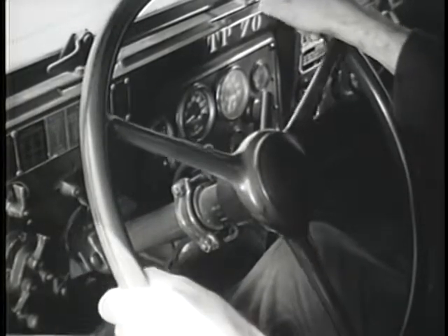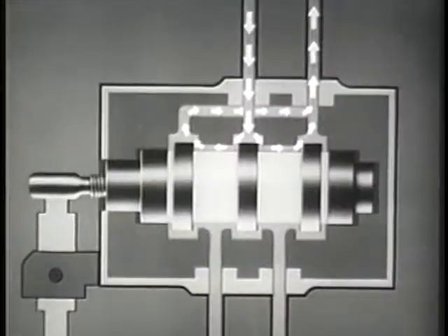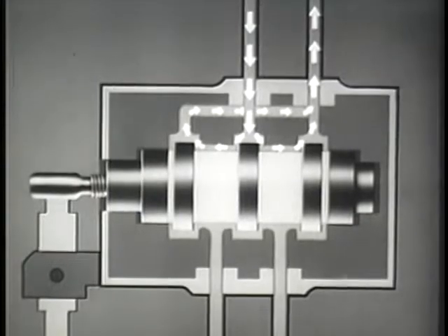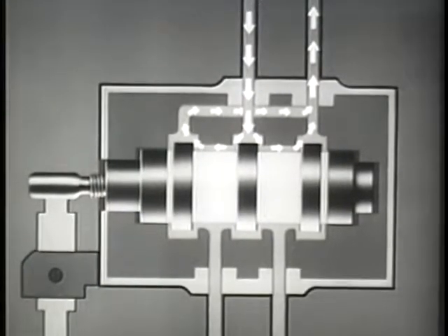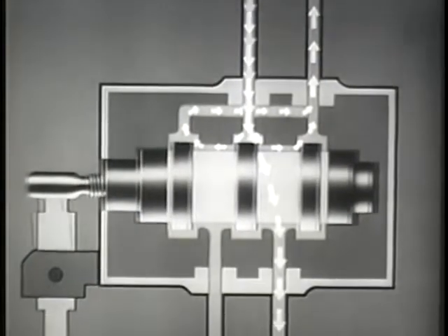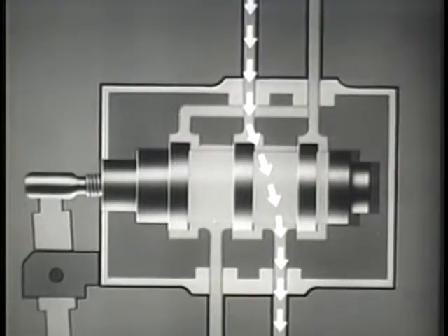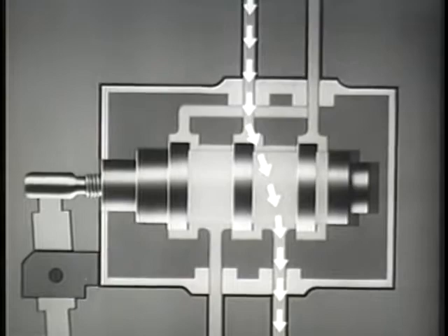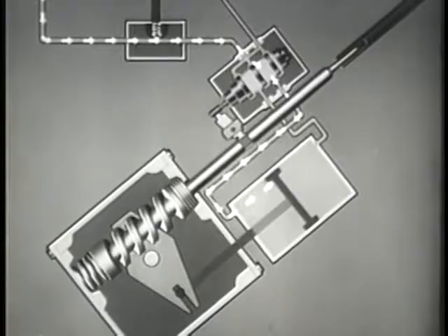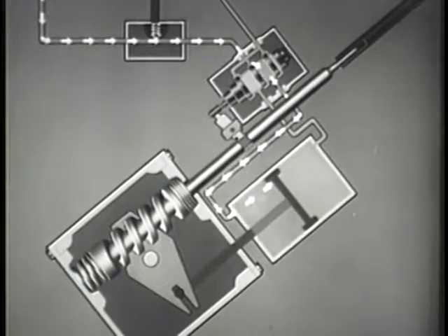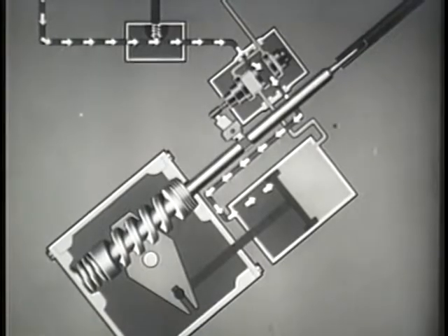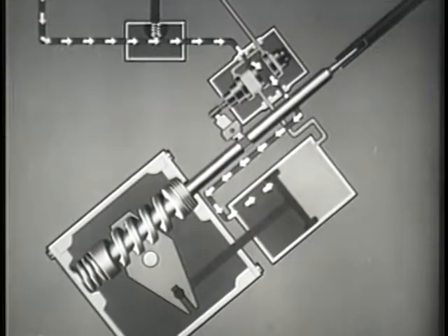As the steering wheel is turned, the up or down movement of the cam actuates the control valve lever, shifting the position of the valve spool. The spool lands corresponding to ports on the valve housing direct the flow of fluid from the pump to the power cylinder. This flow of fluid causes an immediate pressure increase on one side of the piston in the power cylinder.